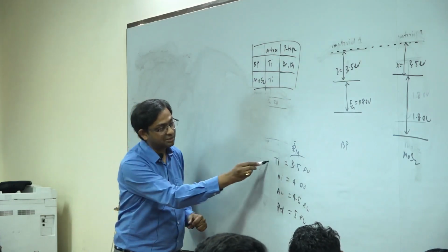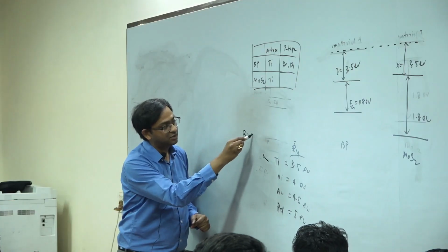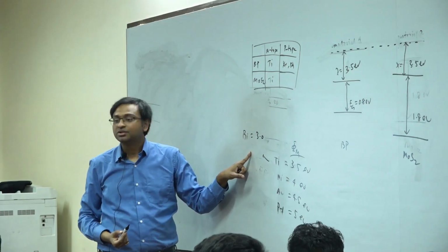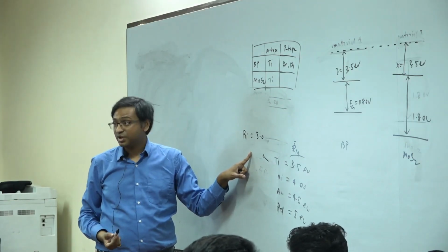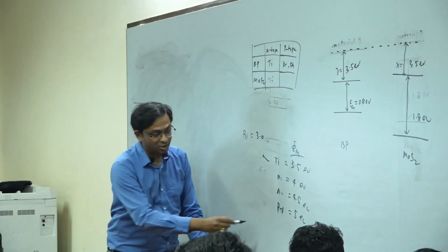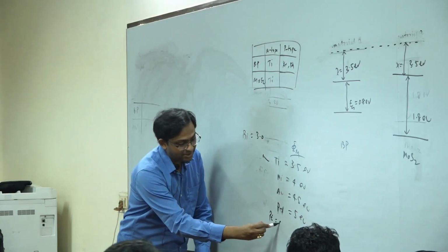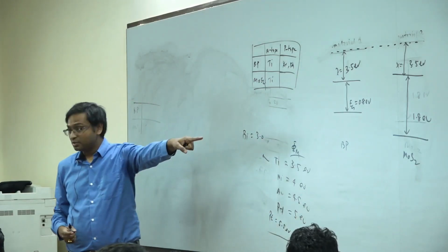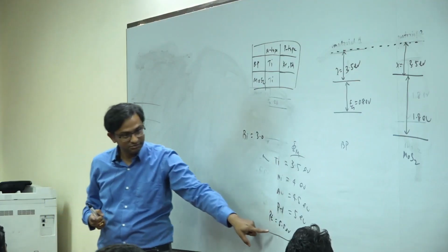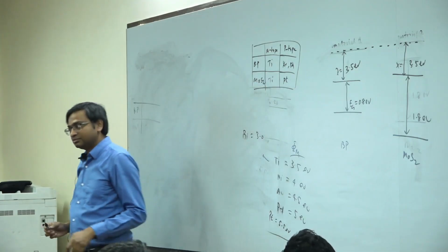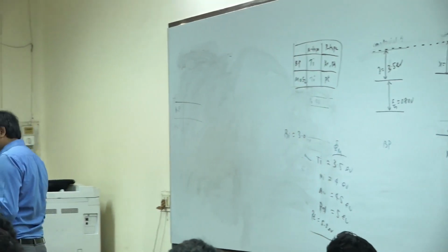You may actually go to something like bismuth, which is 3. That is a good one. Or antimony, correct? Yeah, minus 0.5, even better, right? I mean, you can probably go to something like platinum and maybe get to 5.5 eV. Okay, then you might be able to make a P type contact. You see, right? So then platinum could come here, correct? So you see, just doing metal work function engineering alone is not good enough.